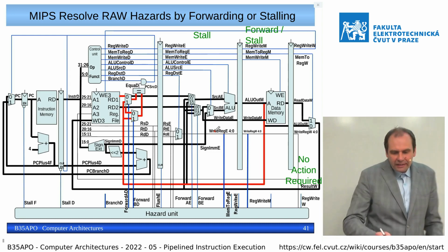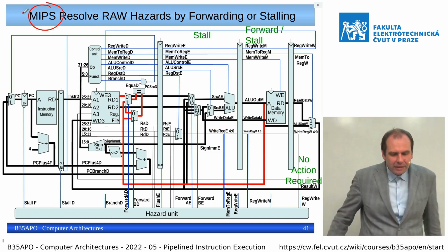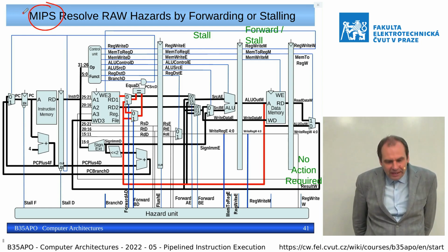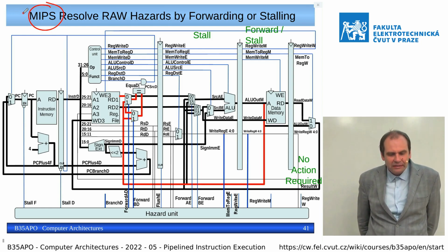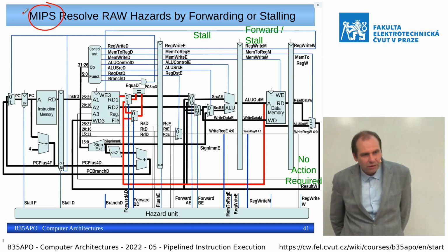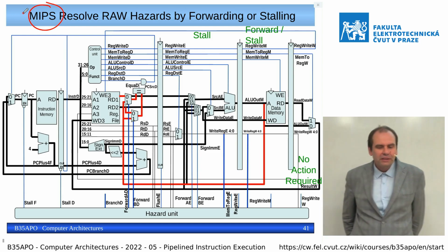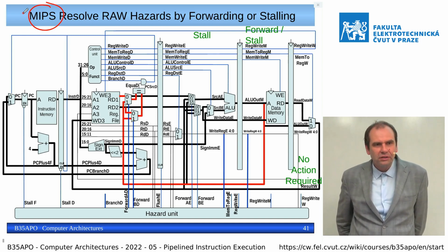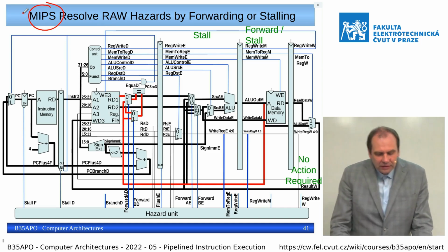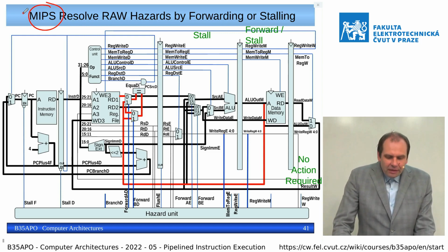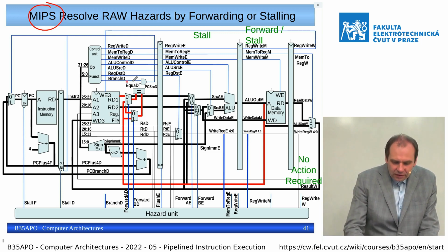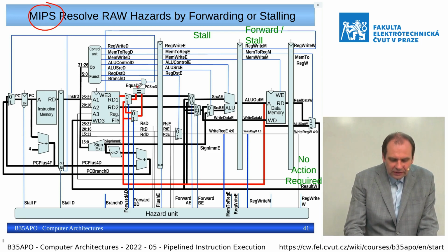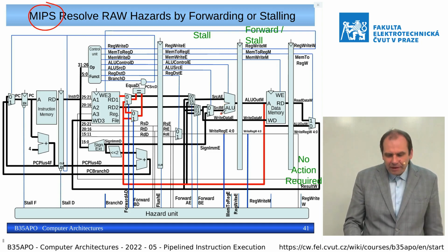This way they really implemented MIPS as a machine with no interlocked pipeline stages. That is the name of MIPS, basically a design which doesn't need to stall the CPU in any case. Okay, it still has one problem, that a condition in the branch can depend on the directly previous instruction.